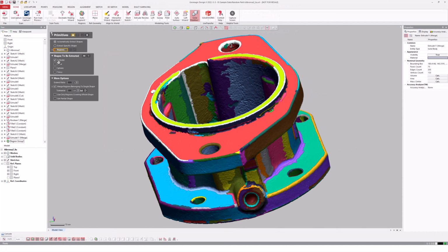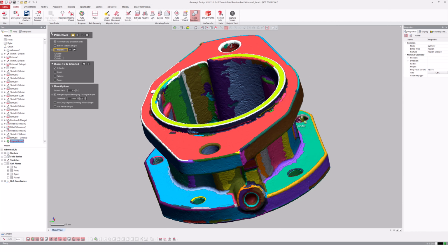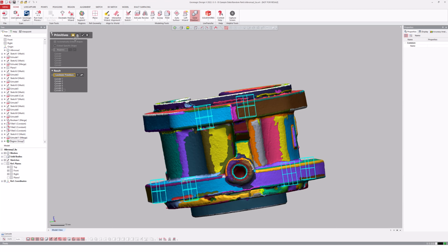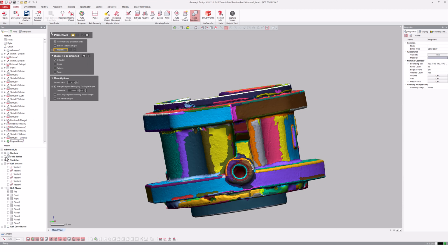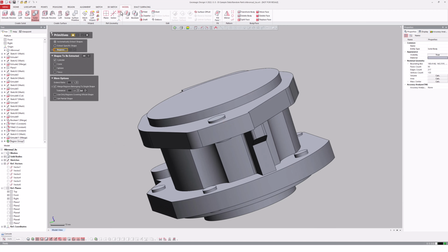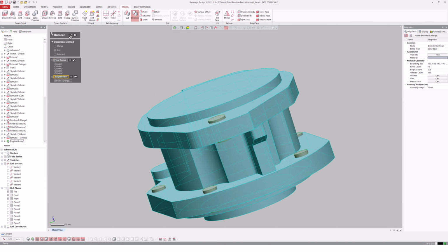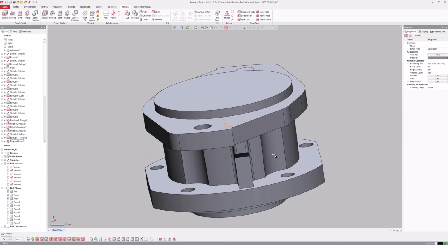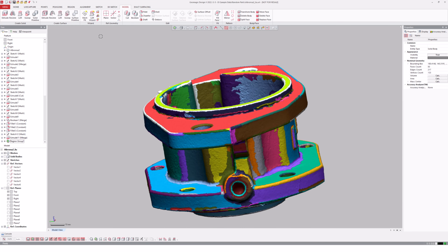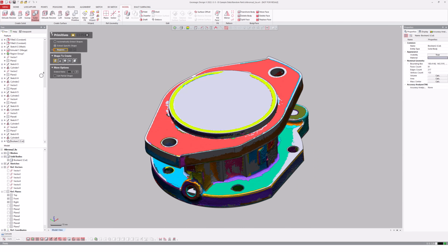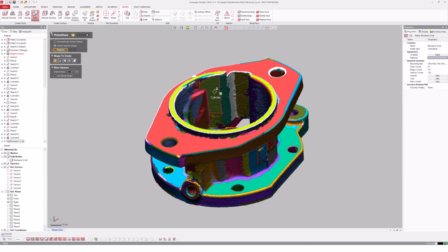These create solid and surface bodies from mesh regions in a similar way to the other wizards, only that the surfaces will always be perfect planes, cones, cylinders, tori, spheres, and boxes. The automatically extract shape option allows multiple surfaces to be fit to selected regions with the desired geometry very quickly, or one or more regions can be selected to extract one specific shape. The primitive surfaces and solids can be extended beyond the bounds of the regions they're extracted from, and a partial cylinder, sphere, or cone can be revolved instead of the full 360 if desired.